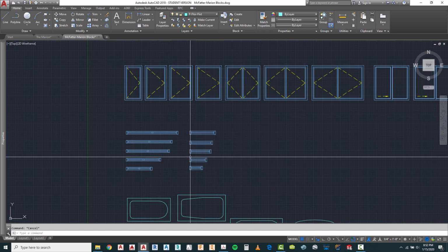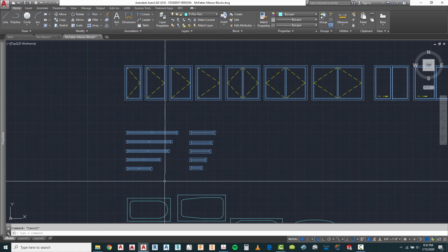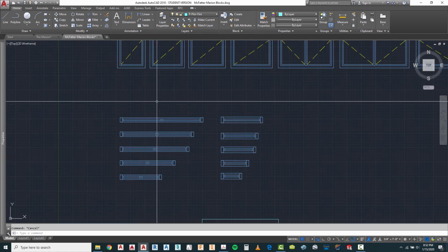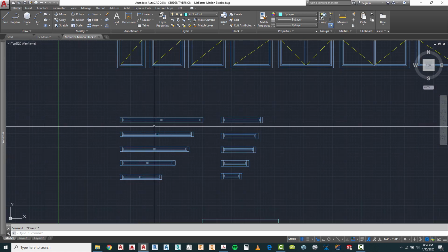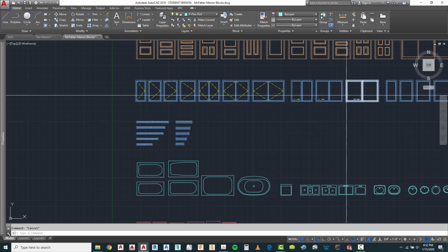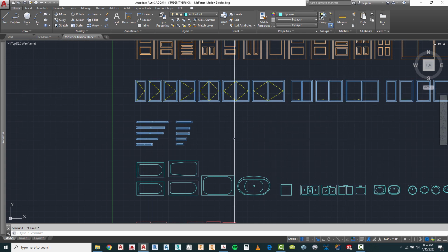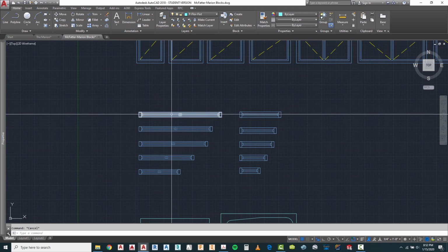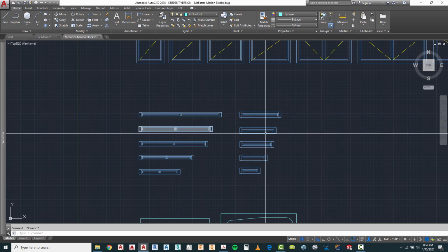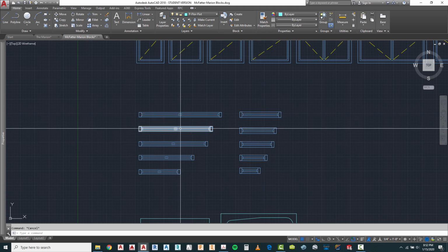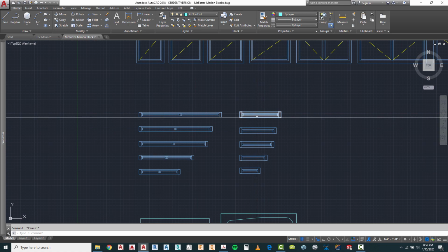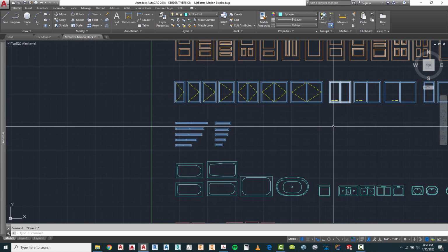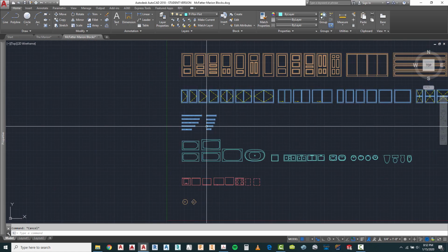Now, we are going to be using one standard floor plan or plan layout for the windows, even though in reality each one of these would be seen a little bit differently. Again, because we're presenting this in a 1/4 inch, we're going to simplify, just have one window type that is shown. There's going to be singles in here and doubles in here, and this symbol will represent any one of these window types that we have.